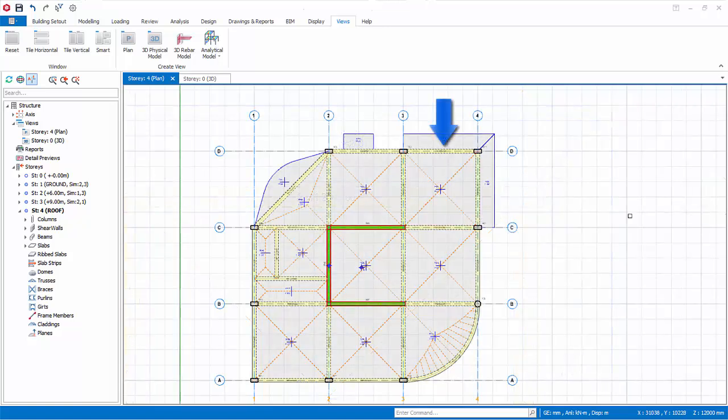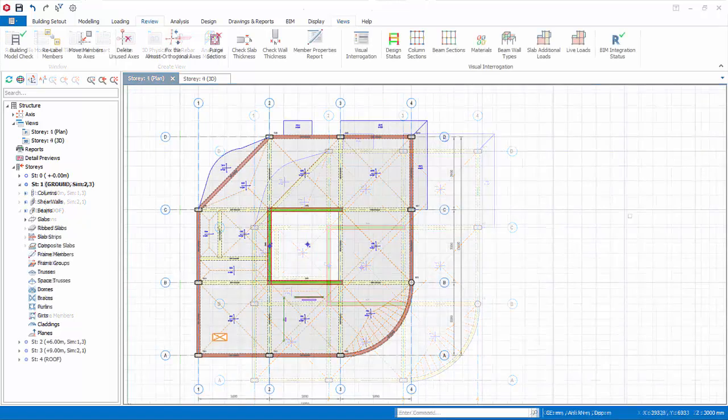For beams, after labeling the last horizontal beam at the top right, the labeling continues for vertical beam. The first vertical beam label will continue at the bottom left. The label will then increment vertically. Then the labeling will continue along the next vertical axis on the right until all vertical beams are labeled. The last vertical beam label will be at the top right.